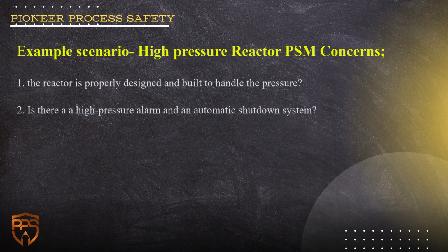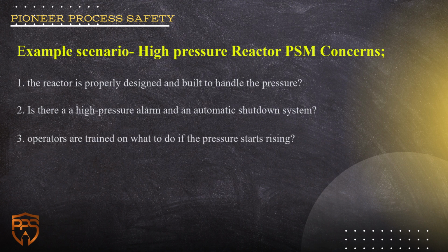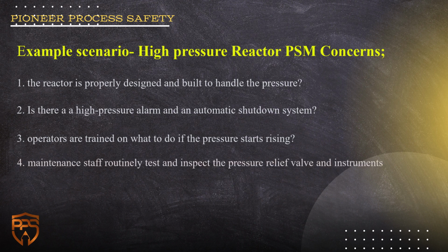That is engineering control. Operators are trained on what to do if the pressure starts rising. It is a layer of procedures and training. Maintenance staff routinely test and inspect the pressure relief valve and the instrumentation devices. That is a mechanical integrity check.